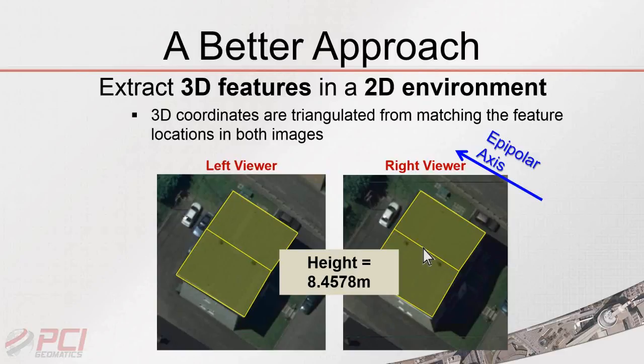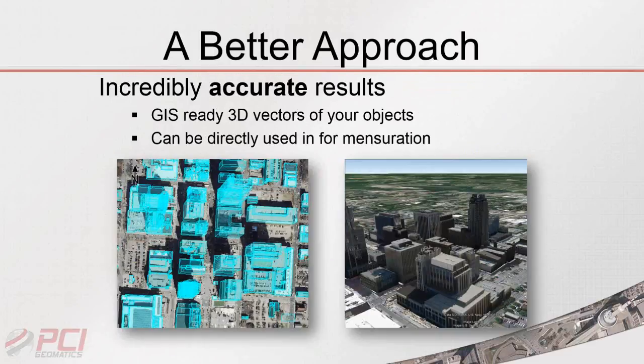So really the big benefit is you can get very accurate results. Like I said, the input imagery is really going to drive the level of detail that you can achieve in terms of pulling out different objects. On the left here we see the wireframe geometry that's been extracted out, which we actually provided to Jeff, and he'll show you that in a minute, how he can bring the more detailed models back into CityEngine and share them out.